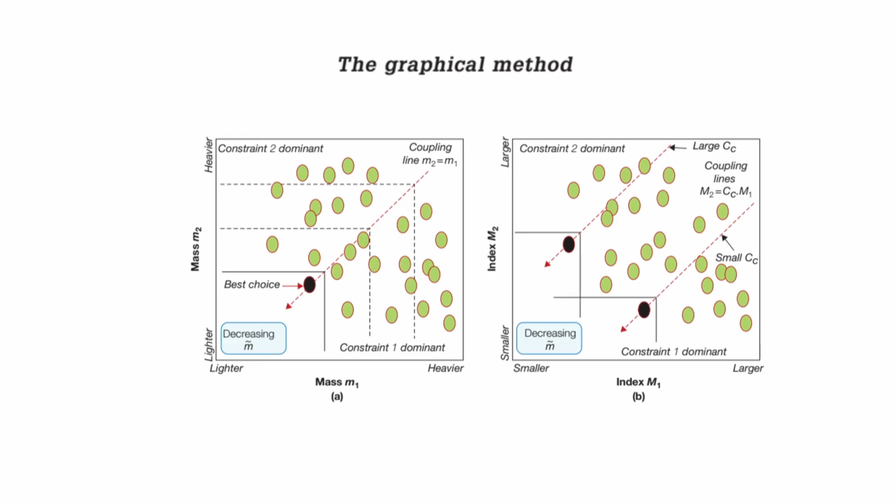Another way we can do the same problem is that there is a conflicting objective. So, you can use a Pareto optimality and you can get a Pareto optimal front. So, you have mass of M2, mass of M1 and get the Pareto front and figure out what are these choices at the Pareto front, like this, at this point comes out to be the best solution of the problem.